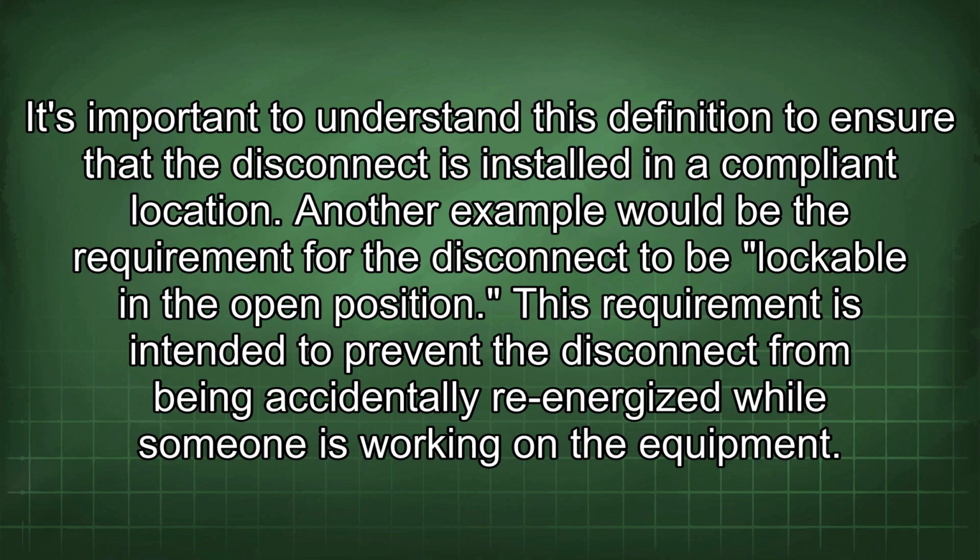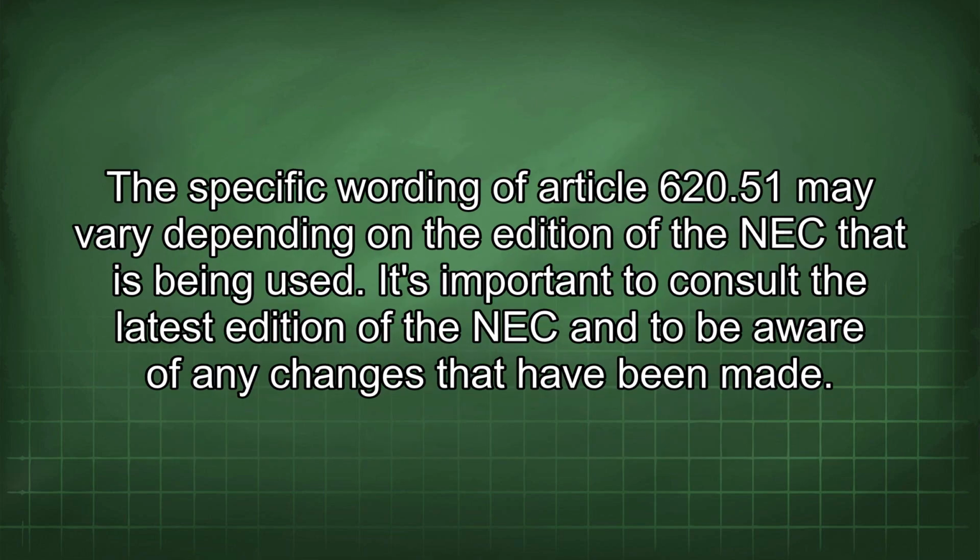Another example would be the requirement for the disconnect to be lockable in the open position. This requirement is intended to prevent the disconnect from being accidentally re-energized while someone is working on the equipment. The specific wording of Article 620.51 may vary depending on the edition of the NEC that is being used. It's important to consult the latest edition of the NEC and to be aware of any changes that have been made.